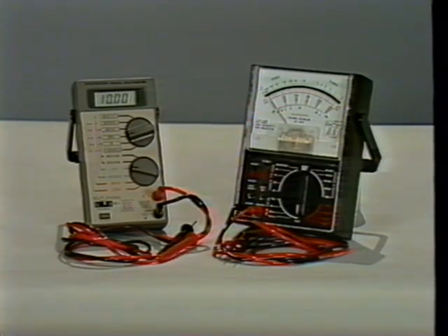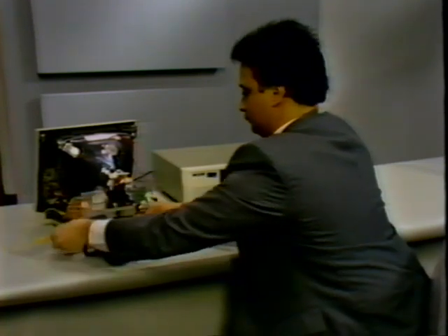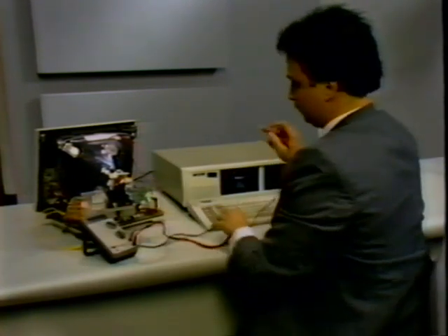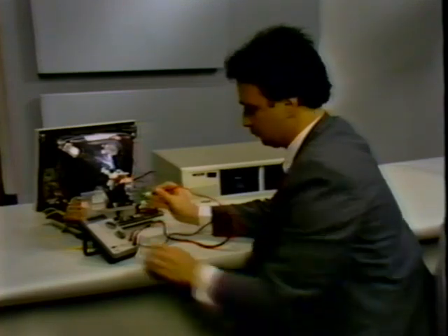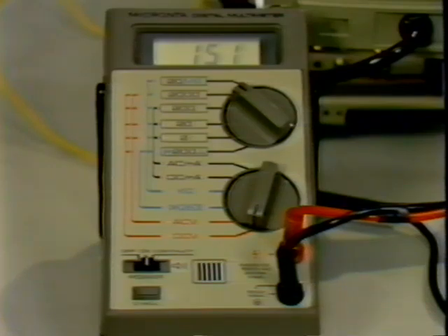There are two distinct types of multimeter, digital and analog. The digital meter displays readings on an LCD or LED screen, while the analog meter uses a magnetic movement and scale. One advantage that a digital meter has over a passive analog device is its high stable input impedance, usually 10 megohms or greater. This high impedance decreases loading of the circuit under test, which makes the digital meter especially useful for measuring high impedance circuits, like this monitor.